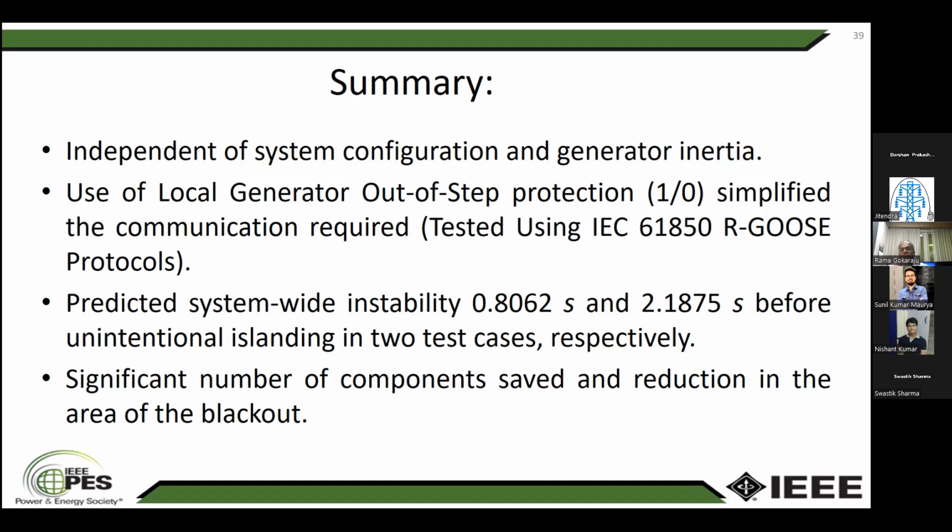We would have to have the full-scale PMU measurements to find the inertia. Here, when we did the implementation, it did not depend on the generator inertia factor. So that was one key advantage. And it also did not depend on the system configuration. System configuration here is the network topology.